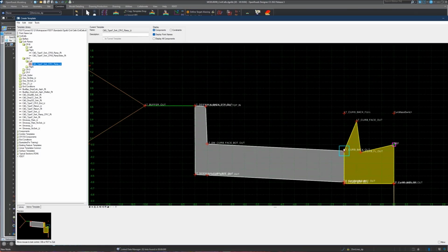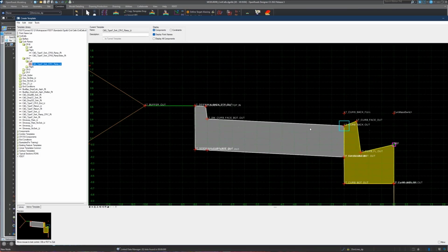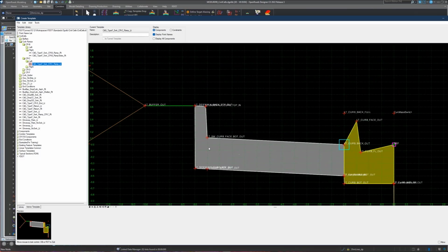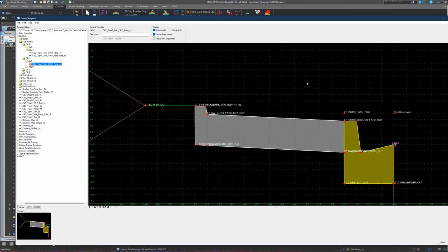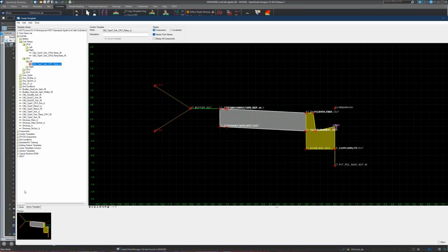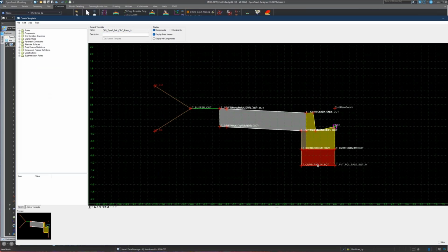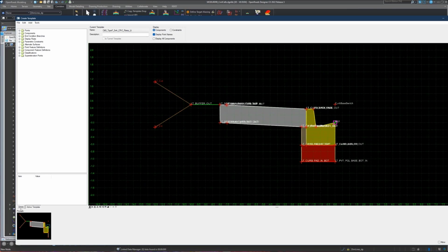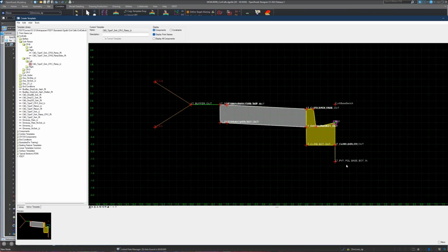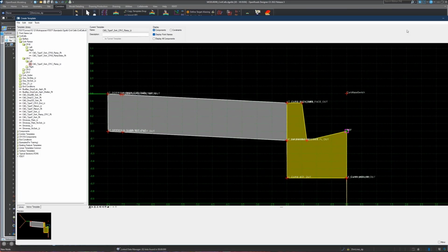And so if I drop this down to, what is it, 0.02 times, I just put this in my calculator a second ago, 0.02 times 8 inches is 0.0133. So if I drop this down to 0.0133 above that, then I know I've got 2% between the left curb flow line and here, and then that'll be 2% as well. So that's really the only difference, is this is going to drop down and create this little header curb at the back here. And this also has all that extra built-in stuff with the curb pad and all the backfill components. And that's pretty much it.